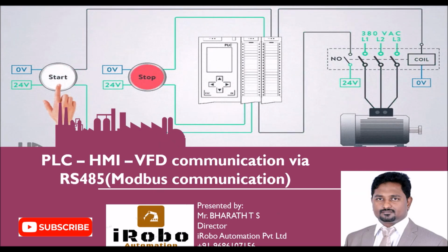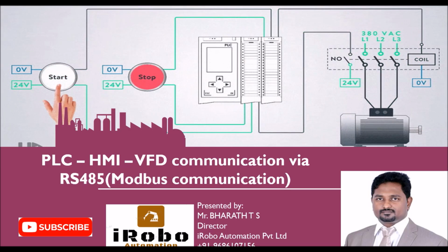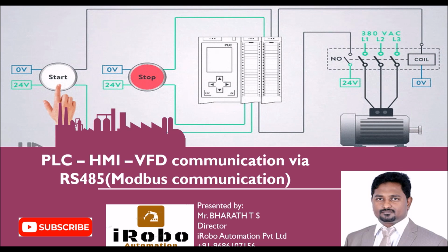So today I'm going to explain how PLC, HMI, and VFD communicate, that is Modbus communication, RS485 communication, so that from the HMI we can control PLC outputs. From the HMI we can control the motor, that is forward, reverse, and stop, and also we can input the frequency from the HMI. Okay, so let us start with the design of the HMI screen first.